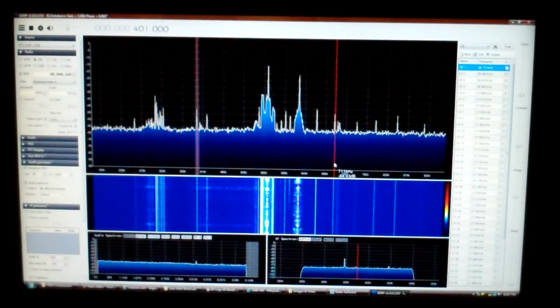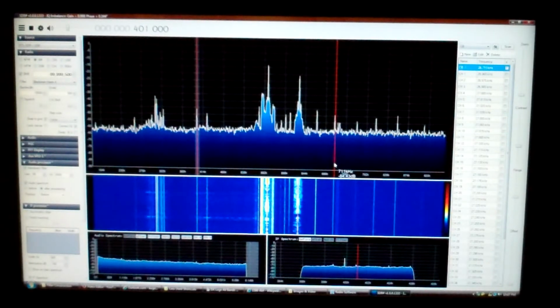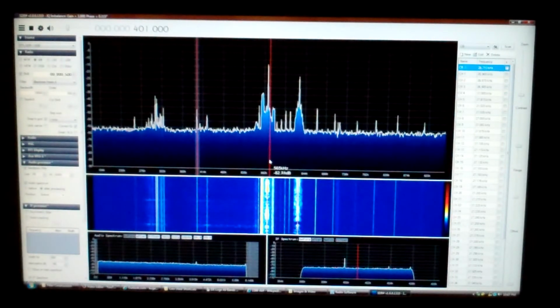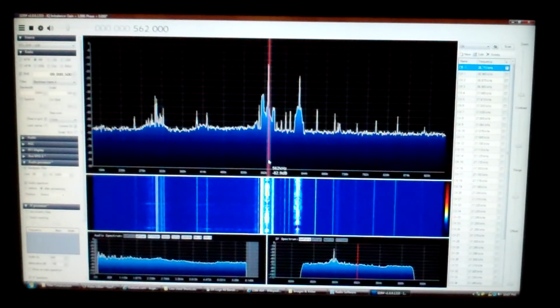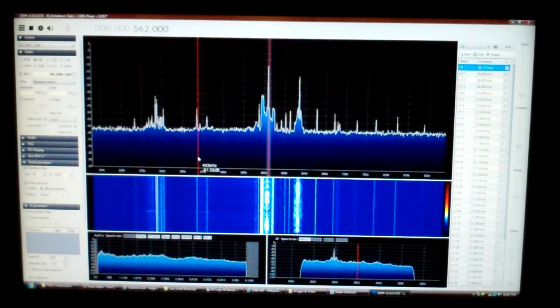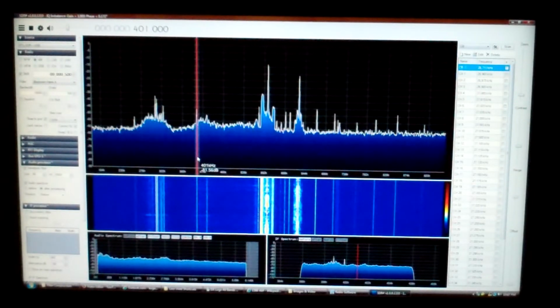Okay, so here's a demonstration of the filter. In order to best do this to eliminate much of the excess AM band, I actually have a low pass filter on this as well, because I can't see on this SDR much of the long wave band, which is this area here, if I don't have the low pass filter on. So basically what you're seeing here is the low pass, what's left of the AM after the low pass, with the low pass in and the 520 kHz high pass filter out.